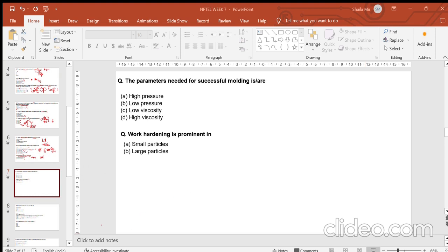And then capital D will be equal to (42.3 divided by 20) squared plus small d. So you just have to calculate. You know the diameter of the balls, it is 10, so you just have to plug in the values: 42.3 by 20 squared plus 10. And that will give you the diameter of the mill.